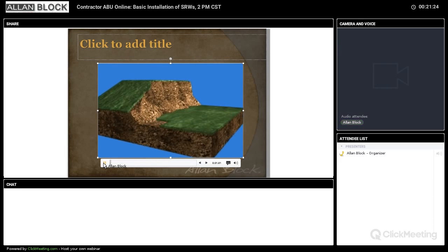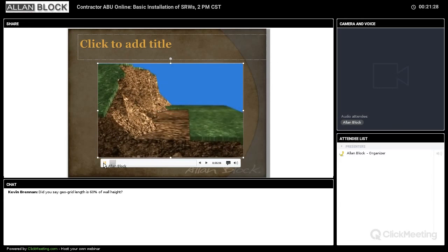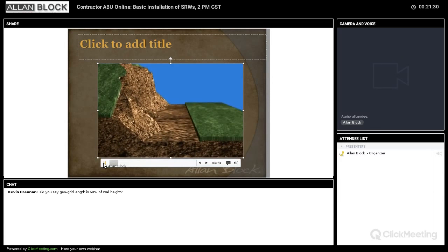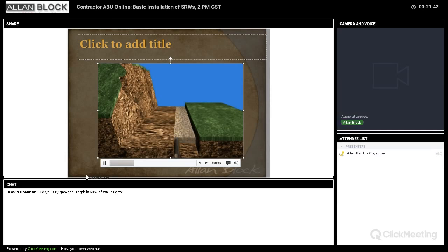We'll take a look at. If only it was this easy and fast. Drain pipe is in place. Material is placed. The only thing this video neglects to do is the compacting of the base of the trench, and I always want to point that out.